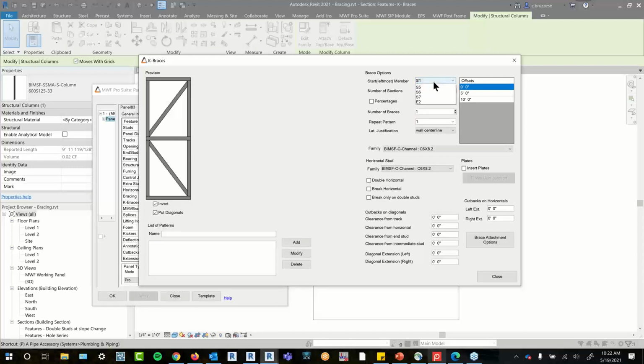So you can span it between different bays, and you could always add in, like the other bracing, as many different variations as you need to. But I'll maybe put this bracing in my first bay, and I'll also invert it and put it in my last bay. And maybe I also want a continuous horizontal running through the panel to meet both ends of the panel. So to achieve something like that, we're going to start off with obviously 2 sections. My leftmost member is E1.